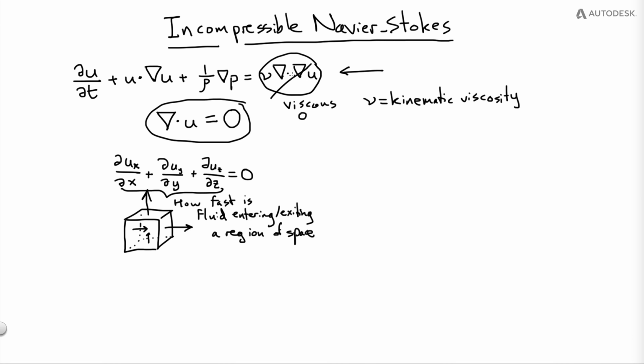Down the road, it turns out that's true almost everywhere except in the boundary layers that develop as flow goes past a solid. Viscosity actually is important there, because even though the kinematic viscosity coefficient is tiny, this other term, the Laplacian of velocity, can be really big. That's a pretty intricate effect. We're going to be tackling it down the road, but for the moment, we just let the solver do its own thing around there, and it looks good enough.